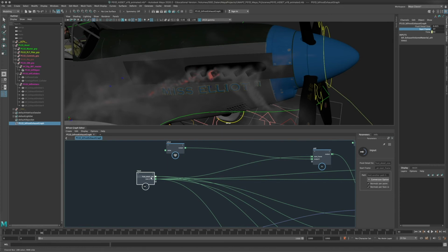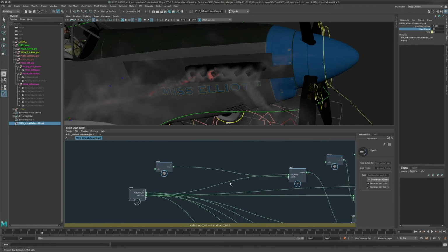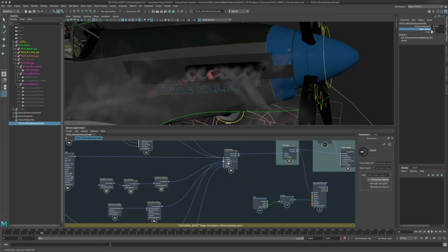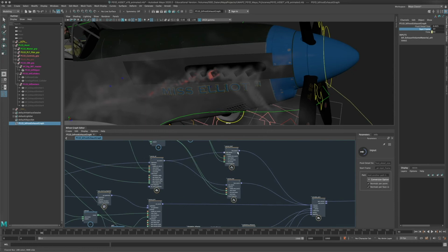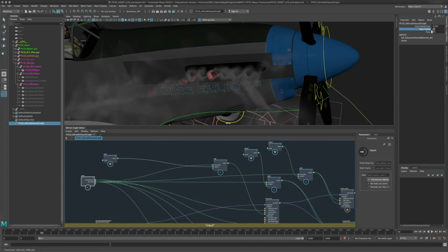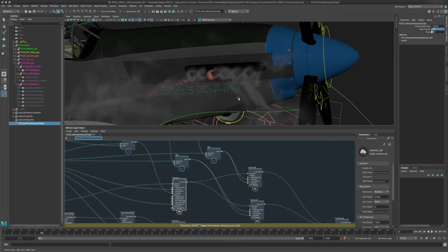So that's an input node, and there's this fluid detail size and the start frame. What I'm basically doing is there's the one simulation at the end, but things get emitted at slightly different times. Based on the start frame that I'm feeding in, which is currently 77, some things will emit 2 to 3 frames before that. There will be some fuel that is emitted a few frames after the initial burst and the like.